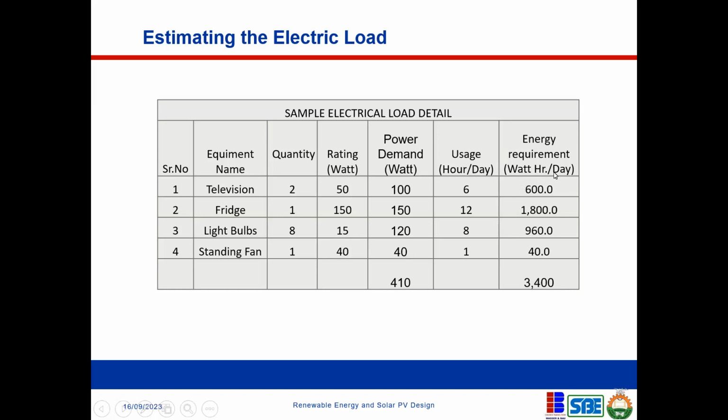So the energy that is required to power that equipment for 1 day will be critical when you're doing your battery calculation, or when you're sizing your battery. This will be very, very critical, because a battery stores energy, not necessarily power. And the power will be critical when you're sizing your inverter. Okay, so this is synonymous to your generator.